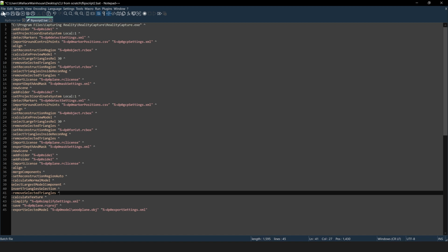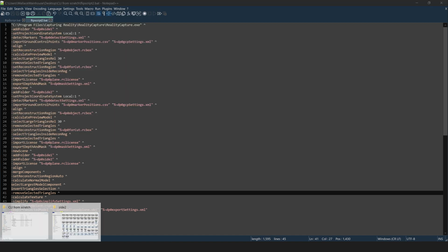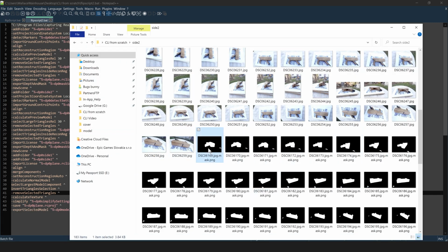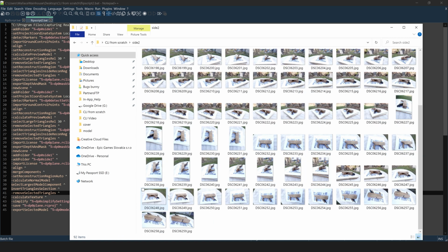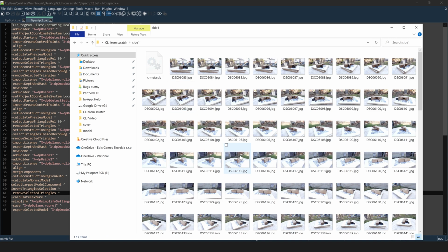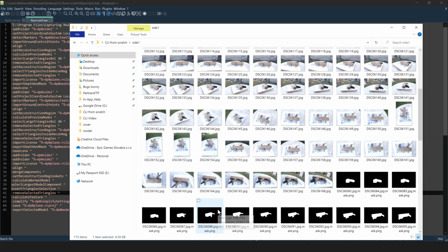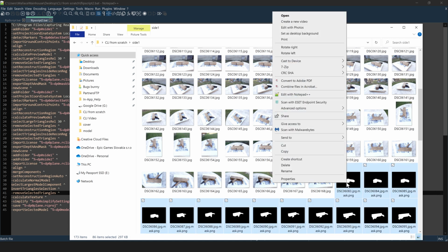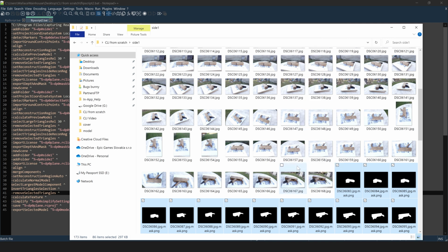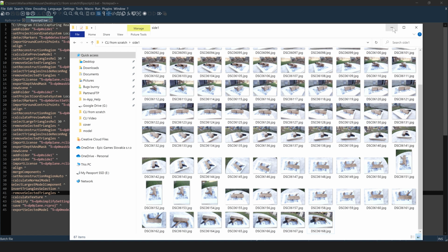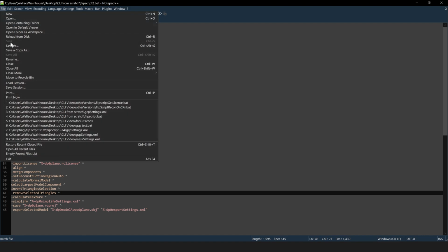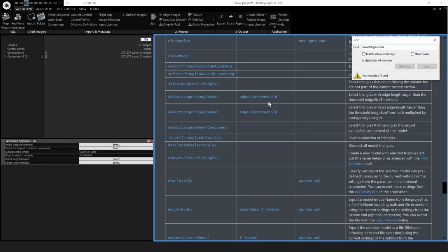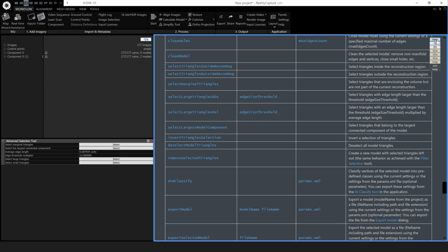So I'm going to save that. Save. Go into side 2. Let's delete these masks. Go into side 1. Delete those masks. I probably could have fixed this by just changing the reconstruction region positions, but I think this is probably a slightly better way of doing it, because you may well end up with some little bits around that need to be got rid of. So the script is saved already. Okay, so let's run the script again, and hopefully that will have fixed it.